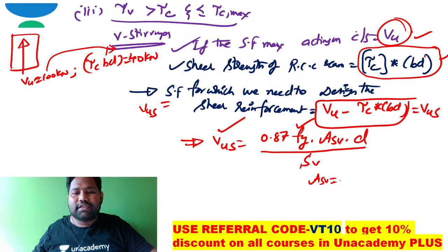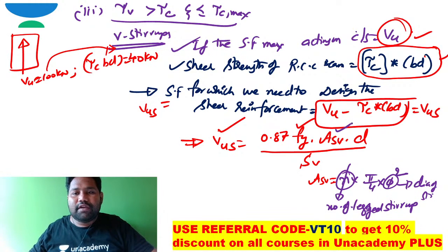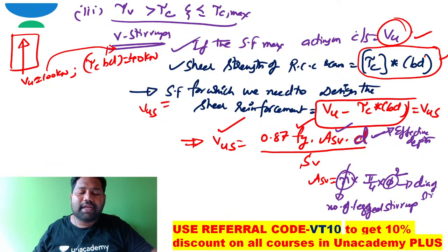If it is two-legged, Asv is n into pi by 4 into phi square, where n stands for the number of legs of the stirrup, and phi stands for the diameter of the stirrup. So you know Asv also. What is d? The effective depth, which is also known from the given problem, as the dimensions will be given. The one and only unknown is Sv.